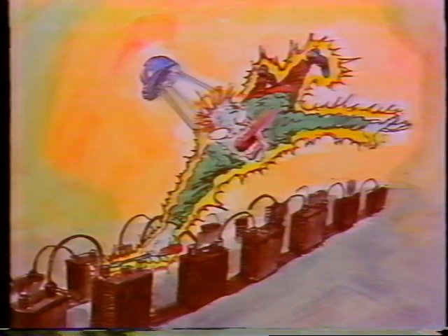Now, one final precaution. A battery cell will short whenever a piece of metal touches both of its terminals. Shorting the battery in this way can cause a tremendous amount of current to flow, with resulting personal injury and serious equipment damage. So be very careful with metal around a battery. Make sure that you use tools that will not accidentally cause a short. For example, a long metal screwdriver would be a poor choice because it could touch both terminals.